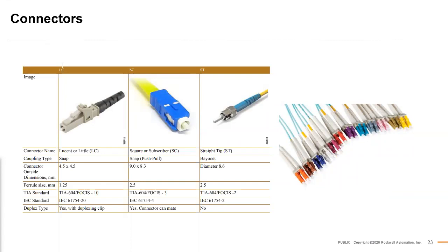But it is very popular these days to do something called fusion splicing, where you use a pigtail, which is basically a fiber optic patch cord that's cut in half, and you melt it to the glass of the trunk cable that you pulled. This used to be a technology only phone companies used, but the cost of fusion splicers has come down significantly, so lots of contractors do it, and it gives you better repeatability when you terminate your fiber.